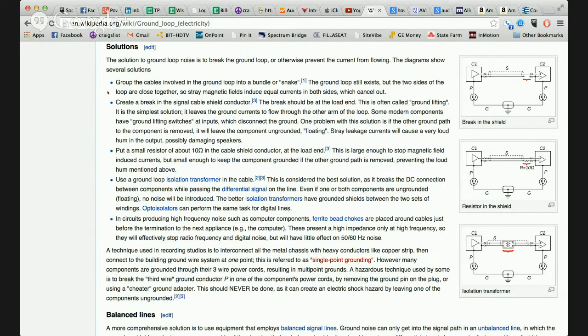or an electrical cable that connects two panels together, electrical panels. It can be the smaller electrical cables that you plug equipment in with, okay? But if you're running those parallel within 3 feet of each other, then that's immediately where I would begin, just because every cable has a magnetic field that it transmits, if you will. Power cables are some of the worst.